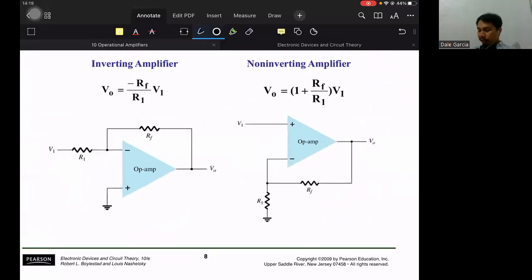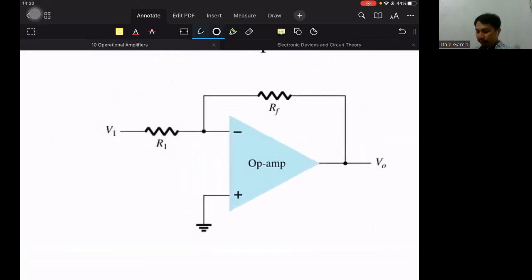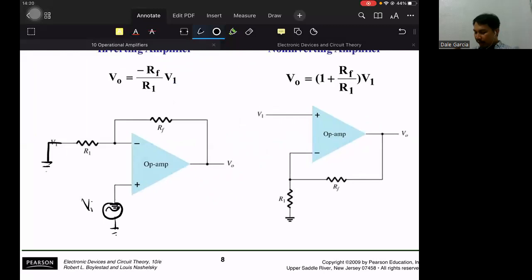So this is the circuit for the non-inverting amplifier. They have similarities, because actually they really are the same circuit. It only looks different because of how it was drawn. But look, class, maybe it's confusing because it transferred the non-inverting input to the top and the negative to the bottom. But if you retain the same manner, the difference between inverting and non-inverting is whether the ground or the input is here. Observe. Is my drawing now the same from left to right?